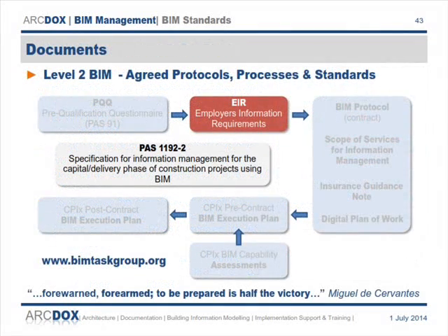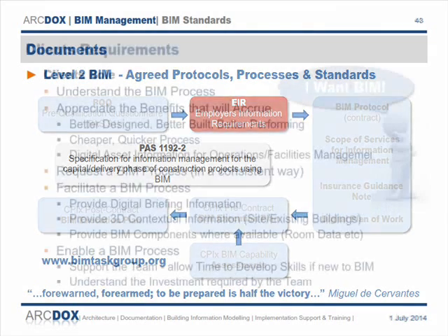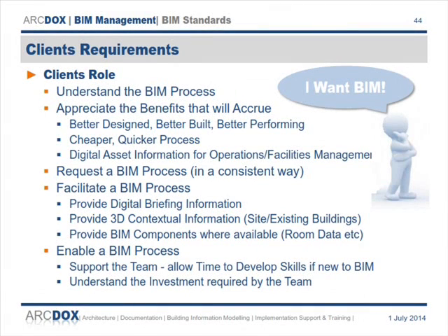The most important document of all, really, in the whole flow of all of this, is the EIR, the Employer's Information Requirements. If you don't have a properly defined Employer's Information Requirements document, then you're not going to get a proper BIM process on the project. This defines what the client wants, and most clients at the moment don't know what they want.